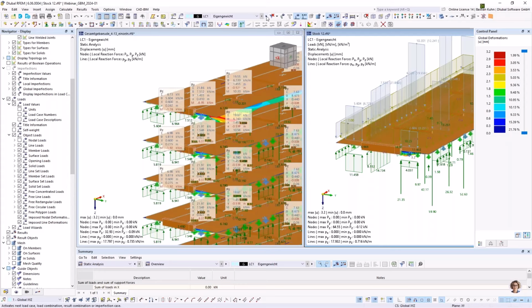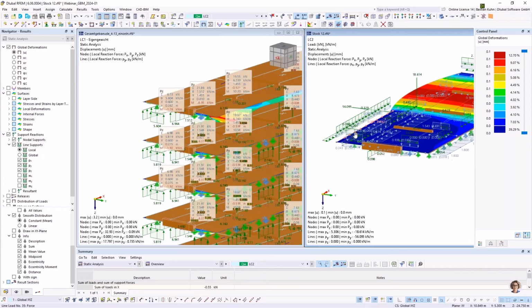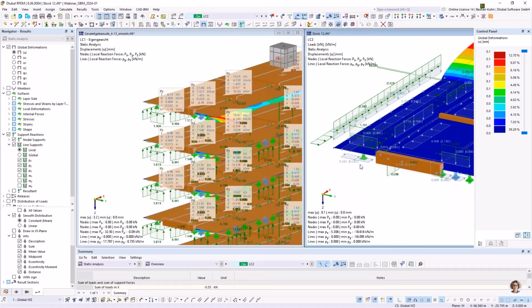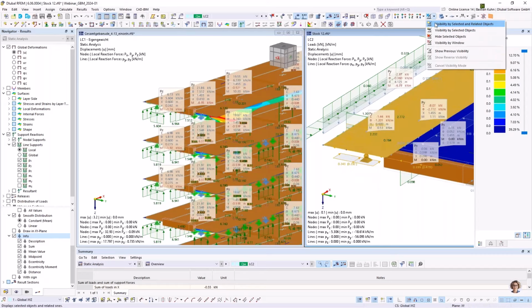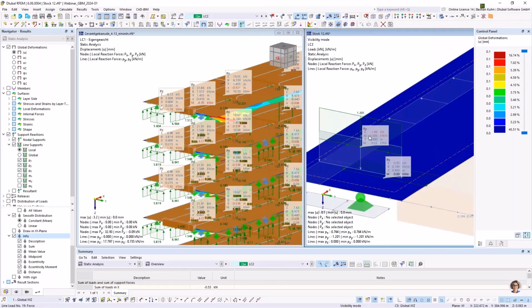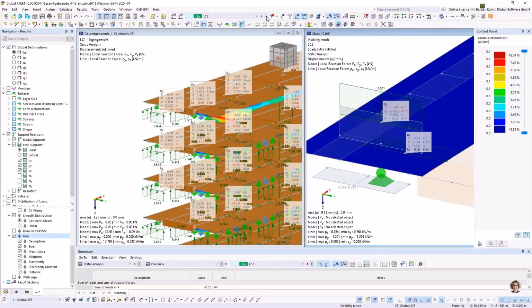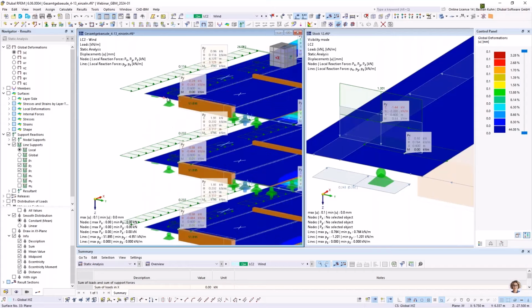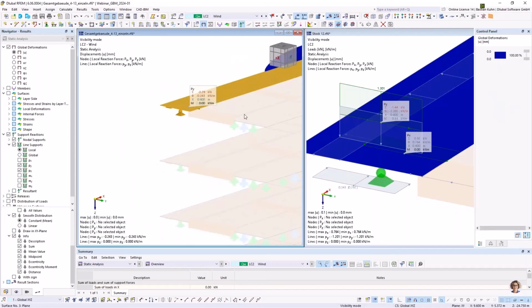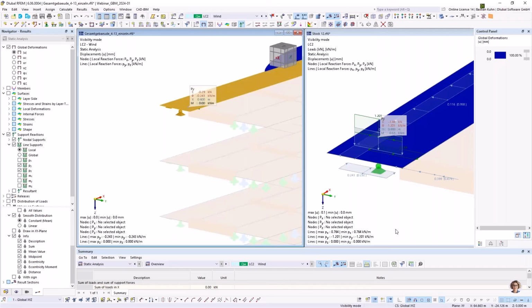Okay, and it can work the same way with the wind load. So when we take the wind, as we did it here for the wind load case, and maybe again we look for the stir case for the concrete kernel, we have here a horizontal force, and here we also can activate the info box maybe, and maybe only visualize this in here. This is now this and this. And when we look for load case 2 in the bigger 2D model, this is this, hold on, do the same in here. You see that, yeah, 0.29 is the sum what we are having here as well. So this fits, and now this is taking this as a load, and the resultant of the horizontal is 1.2. You have to transfer to the story underneath, and so on.